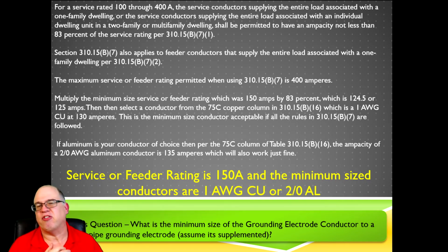Now, if you want to size all the conductors based on 310.15(B)(16), go for it. Again, I work for a company that manufactures wire, so if you always want to go with bigger wire, I'm all about that. You're never going to go wrong. Just be careful about the terminals, because if you go too big, it might not be the right terminals for the job. They have to be listed, labeled and identified for that application and those sizes. Okay, there's my disclaimer.